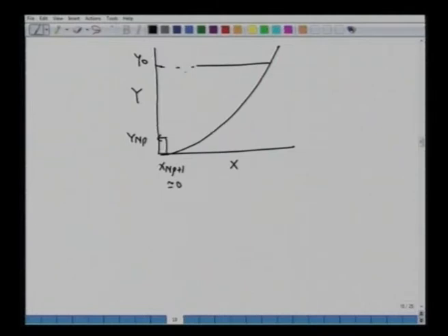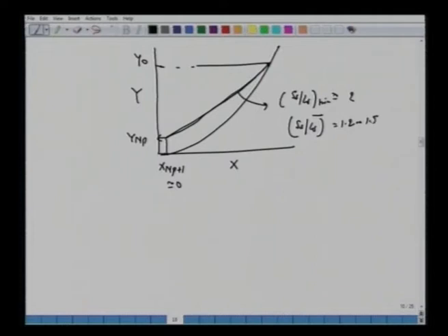And now to find the minimum amount of adsorbent, we connect this, so that's a straight line, which will give us zero driving force here. We can obtain SS over LS minimum, the minimum amount of adsorbent. From this we can then have the operating SS over LS, let's say 1.2 or 1.5 times the minimum amount.